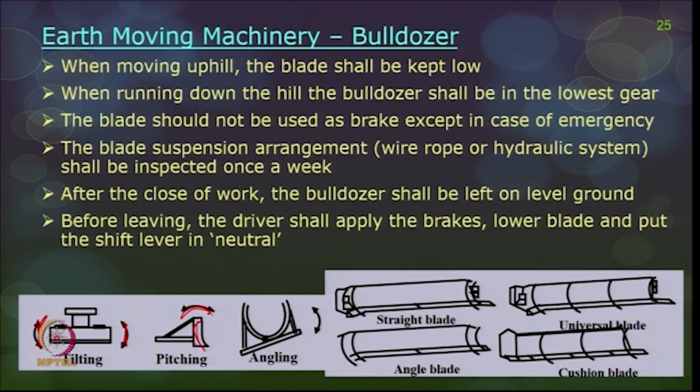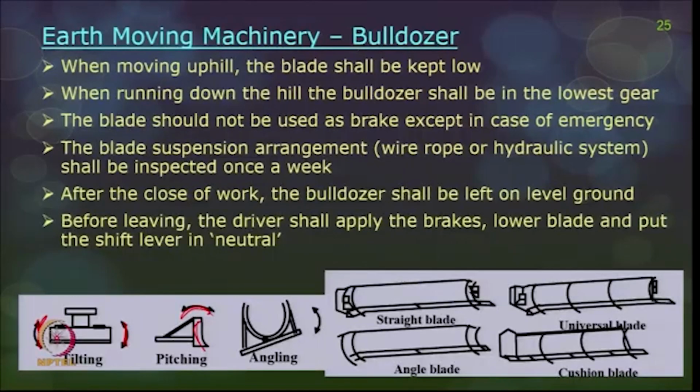Maybe when you are having a curved part of an excavation, then the blade can be pitched so that it is going in a curved path. So, you can tilt the angle of your blade cutting. Angling is the angle with which the cutter blade is cutting the earth, and pitching is the movement too far or too close to the equipment.